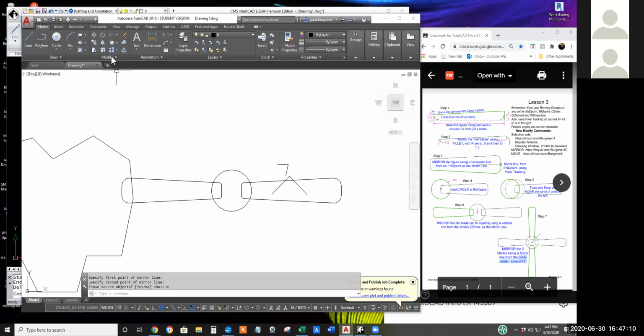I must have bounced off it. Click mirror. Good. Mirror command says select objects. I keep forgetting and holding the mouse down and getting that lasso thing. Precise click. Yep, I got the 2 diagonal lines again. Not a problem. Before I hit enter to say I'm finished, I'll hold the shift key and deselect the 2.